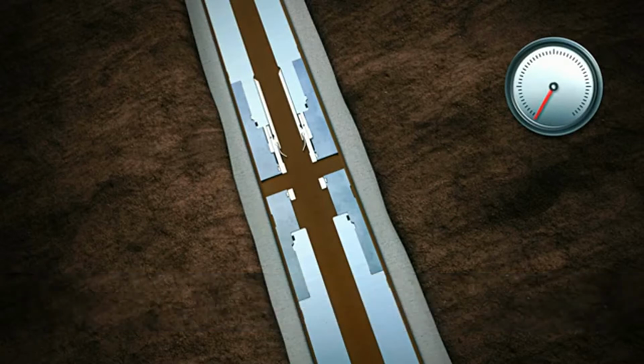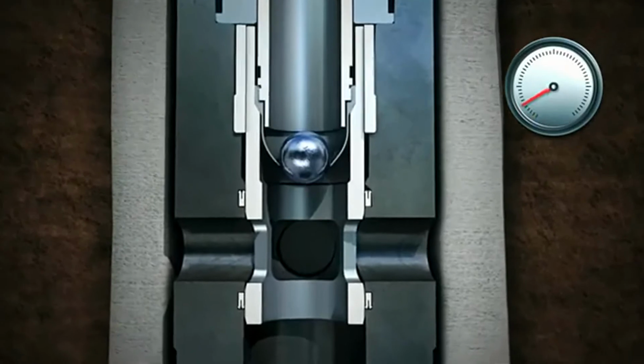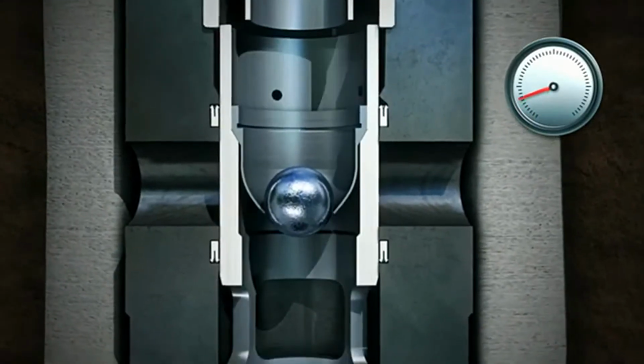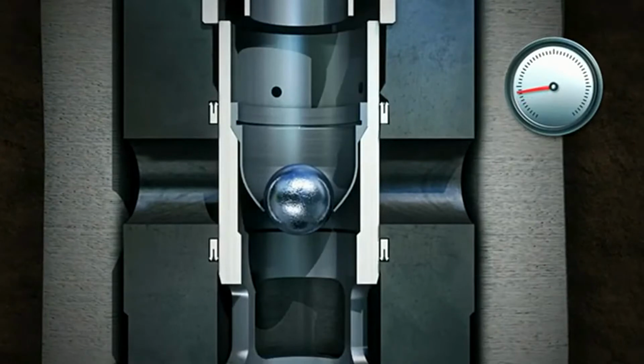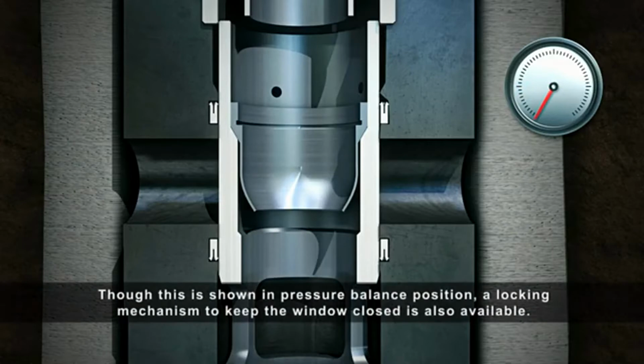After the liner or subsea casing is on bottom or landed out, a closing ball is dropped from the surface. When the ball lands on the seat of the Blackhawk diverter sub, surface pressure is applied to shift the window across the holes in the ported sub. This window will shift at or around 300 to 500 psi, and the ball seat will yield at 1800 to 2400 psi. Though this is shown in pressure balance position, a locking mechanism to keep the window closed is also available.